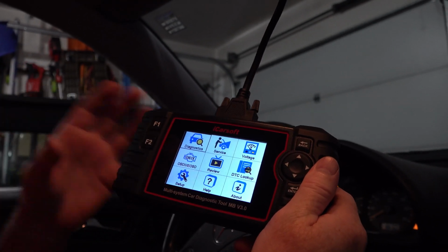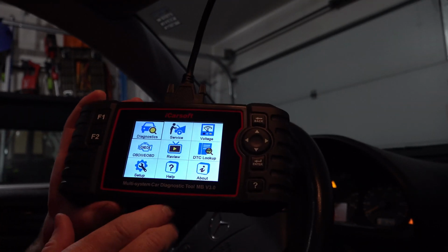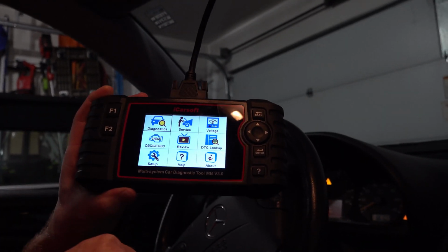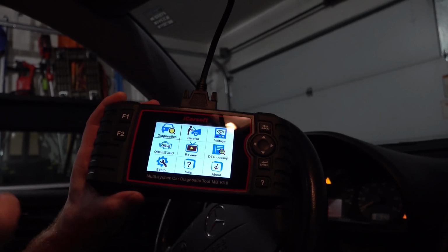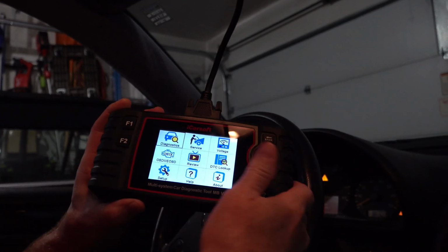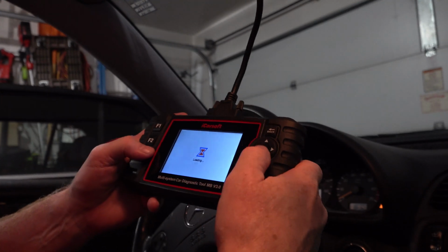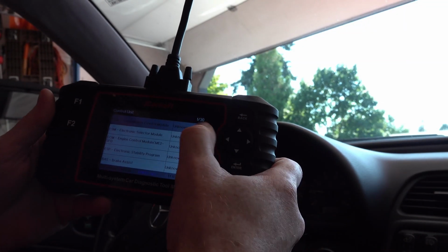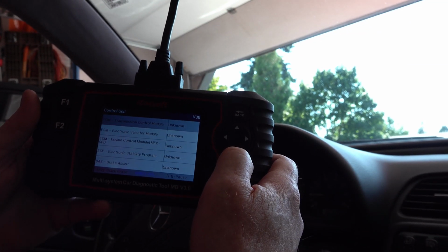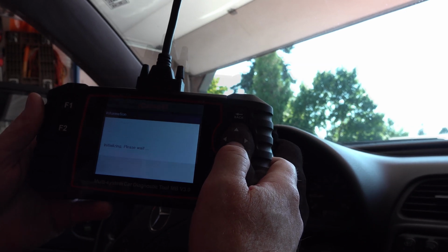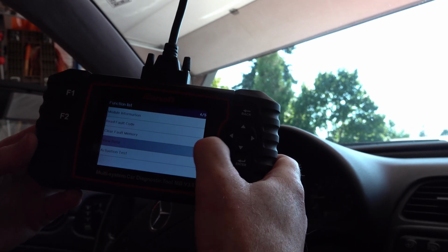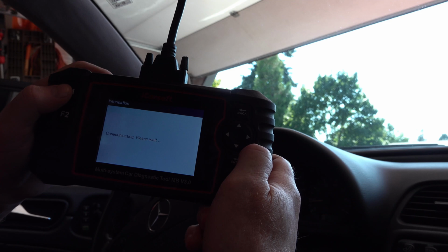Cool. And so I hooked up the computer this way so we could go driving and see what the RPM is. The last diagnostic, and the only one we had on the transmission, is that there was a speed sensor error. So we want to see if it's getting proper speed from the wheels and things like that. Okay. And this computer will tell us that. So we go into diagnostics, we set it up for your car, go to the transmission control unit, which is the one we want to work with. Data, or view data. We're going to go down to view data, hit enter.